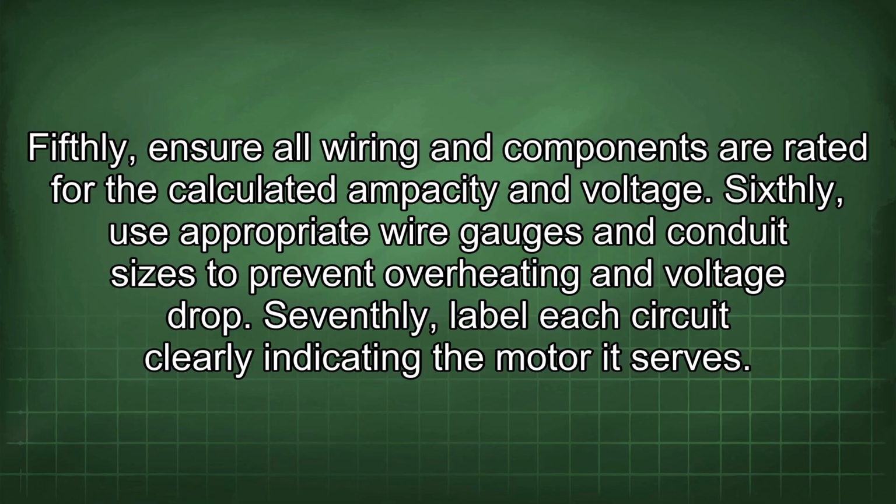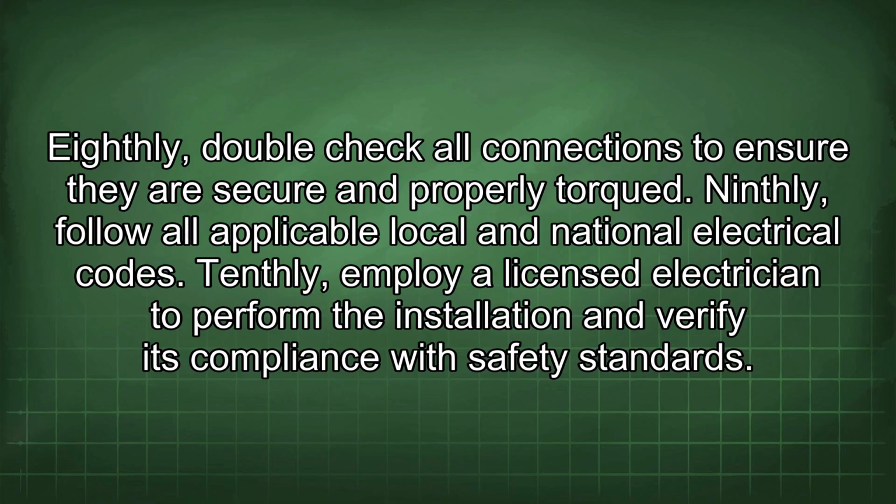Sixthly, use appropriate wire gauges and conduit sizes to prevent overheating and voltage drop. Seventhly, label each circuit clearly indicating the motor it serves. Eighthly, double-check all connections to ensure they are secure and properly torqued. Ninthly, follow all applicable local and national electrical codes. Tenthly, employ a licensed electrician to perform the installation and verify its compliance with safety standards.